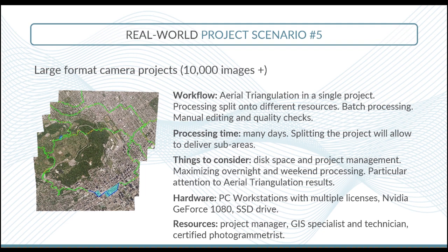So, things to consider in a project like this. Obviously, disk space will be a matter to keep in mind, because for a big project you're going to generate a lot of data. Project management will be very important, so you'll need to plan your project carefully. You will want to maximize overnight and weekend processing, and that's where you may take advantage of batch processing. And you're going to pay particular attention to the aerial triangulation result.